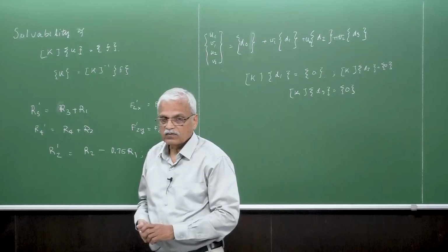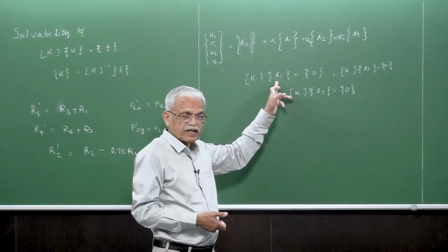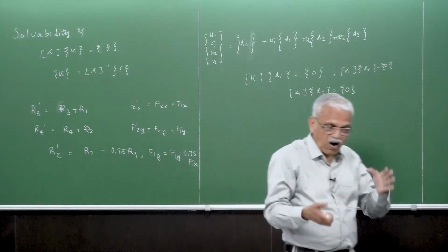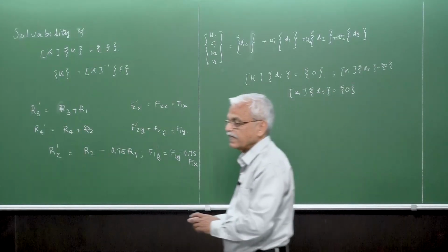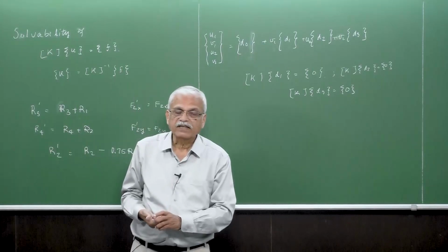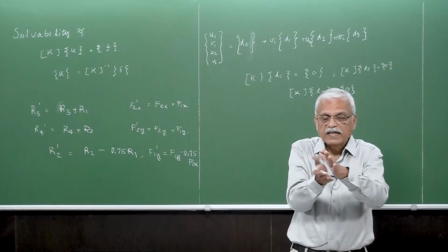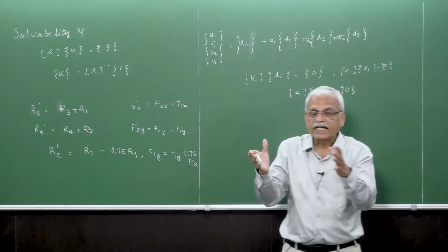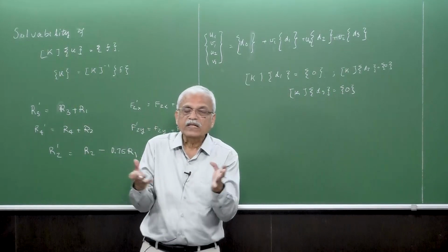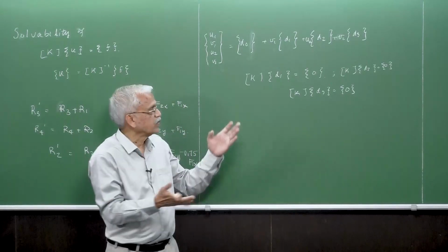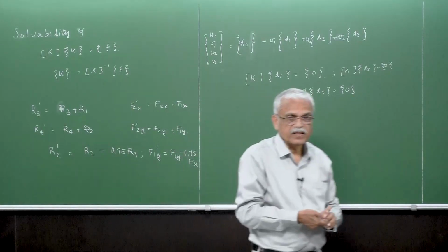So what does that mean? To have the configuration of D1, you do not require any force, or you can extend it further, saying that the body does not have any elastic deformation. It doesn't have any stresses inside. It is moving, but it doesn't have any elastic deformation relatively between the points of the body. So it is moving like a rigid body. That way, D1, D2 and D3 are known as rigid body modes.